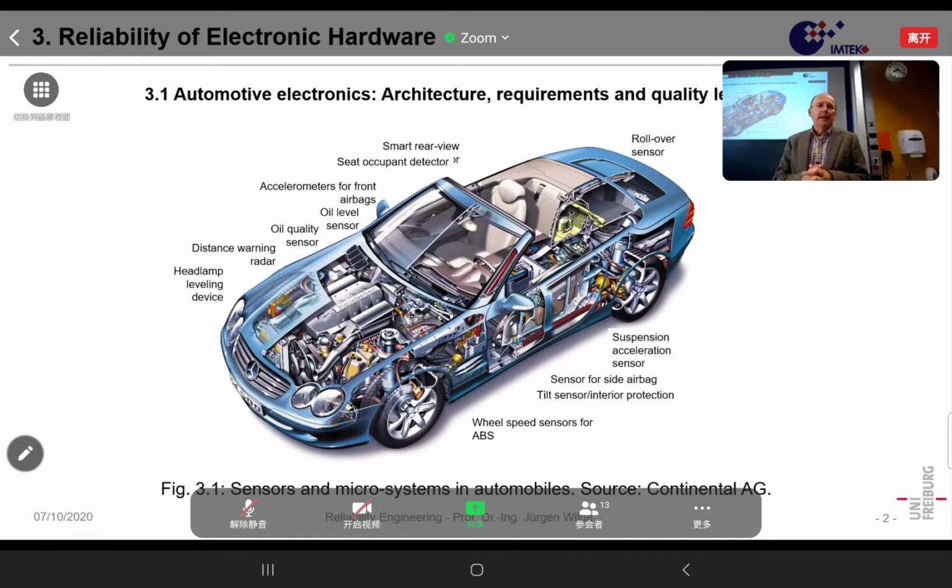And we need also, in connection to that, seat occupant detector, because, for instance, when we have a children's seat on the passenger side of the car, that airbag must be deactivated, and in that way we need to know occupation of such seats.